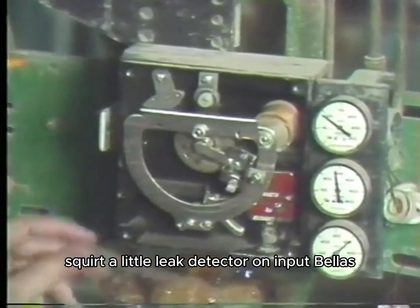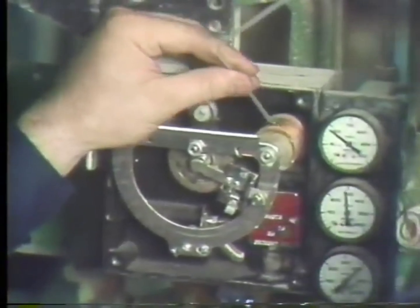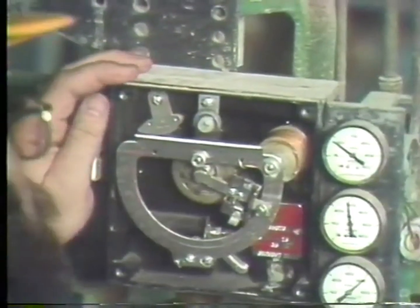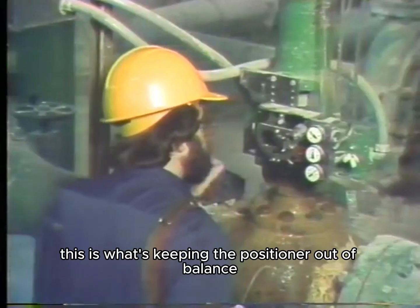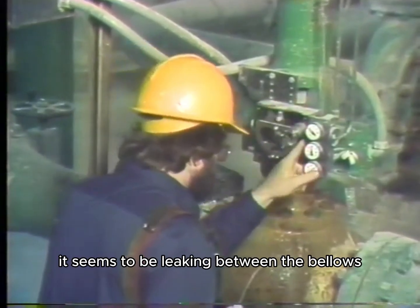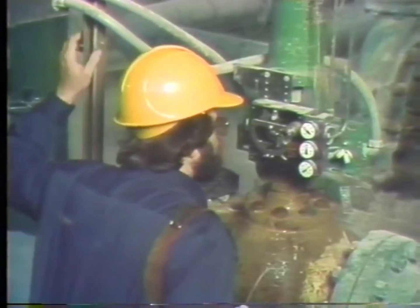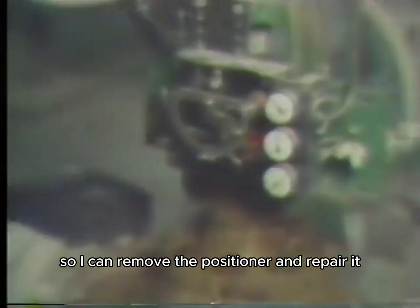Squirt a little leak detector on the input bellows and see if there's a leak in here. Some all over. That ought to do it. There it is. A leak in the input bellows. This is what's keeping the positioner out of balance. It seems to be leaking between the bellows and the housing. It's probably just the O-ring. I'll get the operator to bypass this valve so I can remove the positioner and repair it.